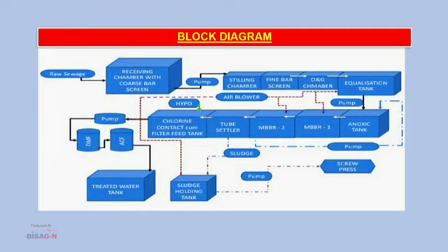Then stage 14, Chlorination. The treated sewage is collected in the chlorination tank and disinfected through hypo. An HDPE tank for hypo solution and its dosing pump are provided for the purpose. Chlorine being a very strong oxidizing agent, a small dose is enough to achieve the desired level of disinfection.